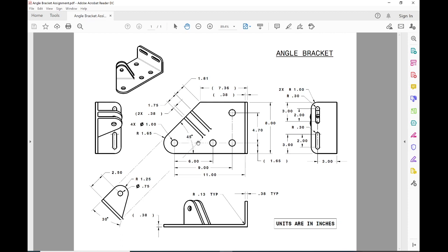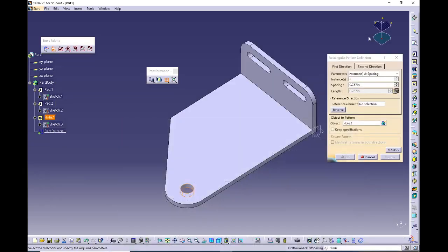So I'm going to go ahead and draw a 4th hole here, and I'm going to make them all 3 inches apart. Then I'll come back and remove that hole because there is no hole here. But just so I can use the rectangular pattern and show you some shortcuts, we're going to use that 3-inch spacing. Okay, so in spacing, I'm going to type in 3.